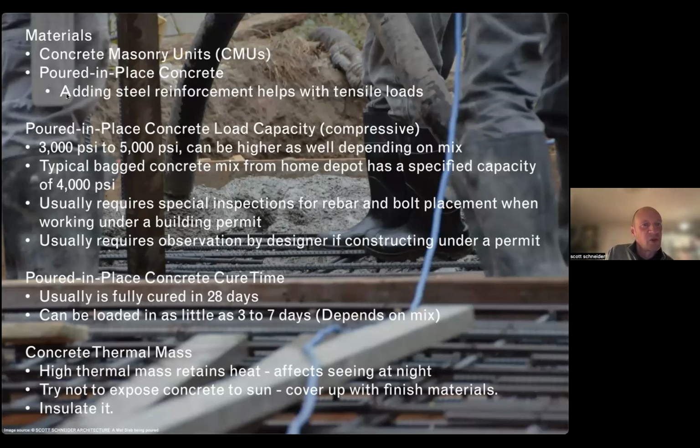Otherwise, materials: we have poured-in-place concrete and then CMUs, which are concrete masonry units. You'd really just be using those for maybe a partial height wall or something like that, but the rest of the foundation you'd want to do in poured concrete.